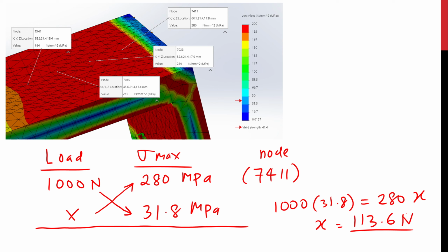So why are we getting these values? Because currently your material model is something called linear elastic. Linear elastic material model means your material is going in a straight line. Even though in reality, if you were to do a real experiment, your material would behave somewhat like this, and then it's going to flatten out, it's going to fail somewhere.